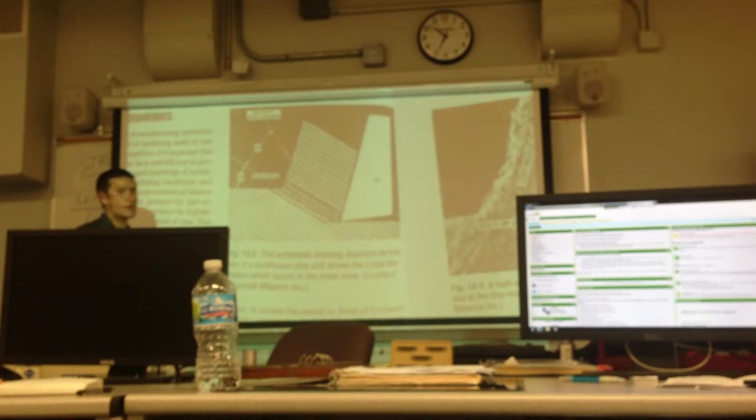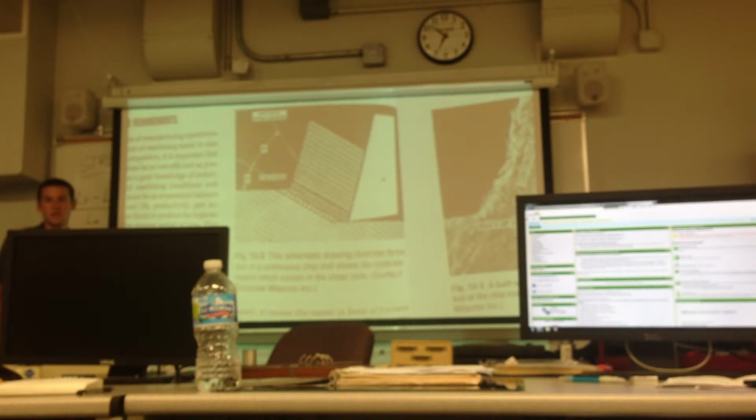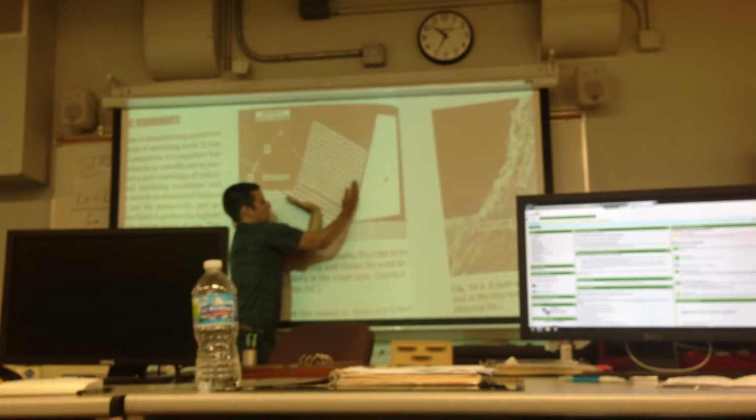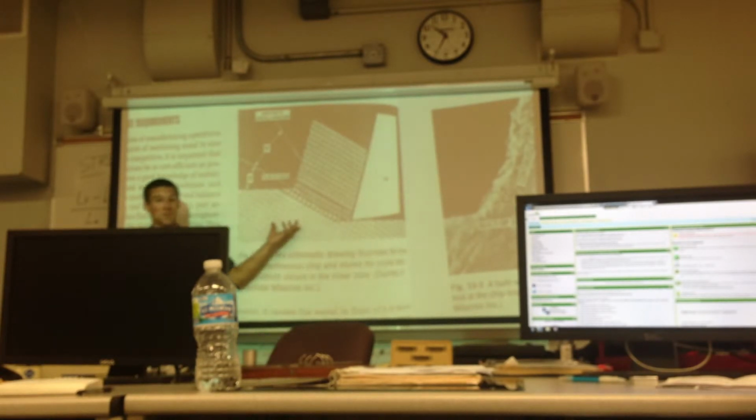What do you mean by smooth? Because you know how you said the lattice is straight, and it will break along that, kind of like the grain. So you said the rake has the ability to change the angle of the shear plane? Yeah, this will move up and down depending on what this is. And it also depends on the material itself.